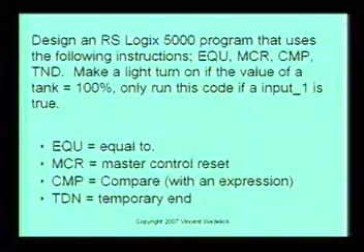Design an RSLogix 5000 program that uses the following instructions: an equal to, an MCR, which is a master control reset, a CMP, which is a compare, and then a TND, a temporary end. Make a light turn on if the value of a tank equals 100%, only run this code if input underscore 1 is true.